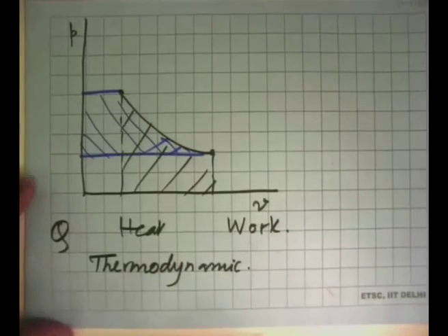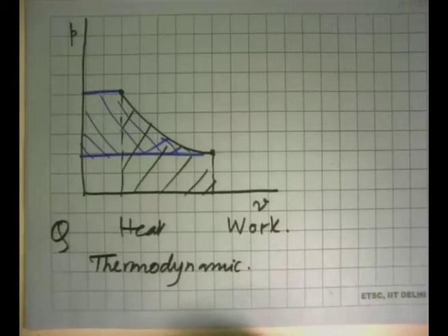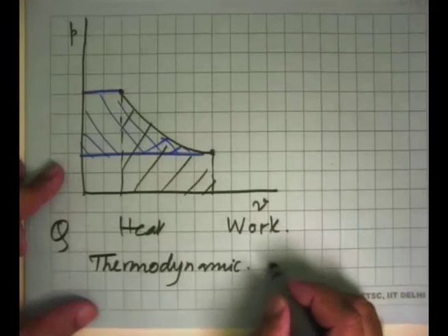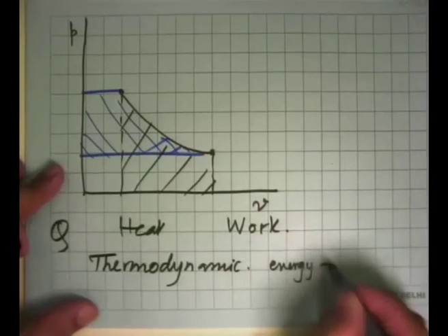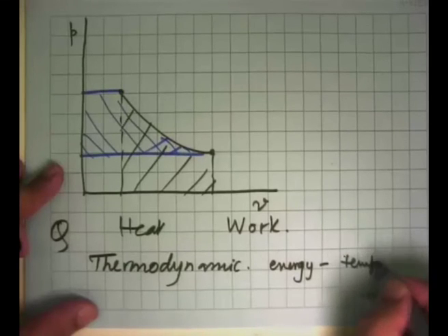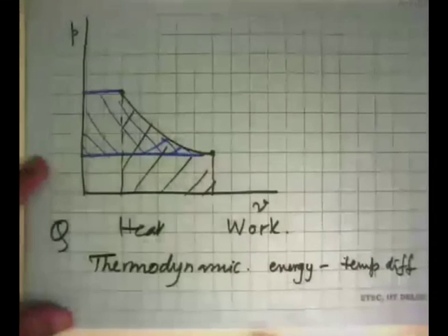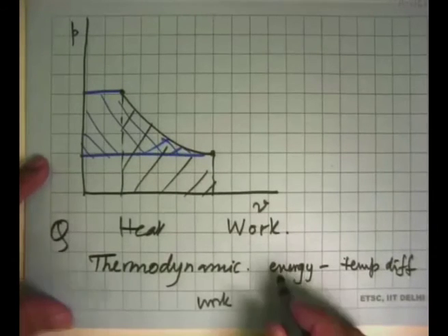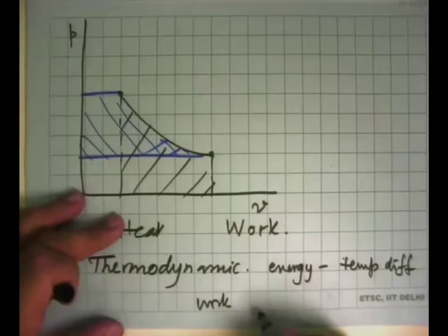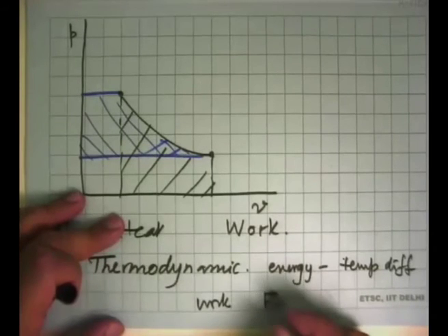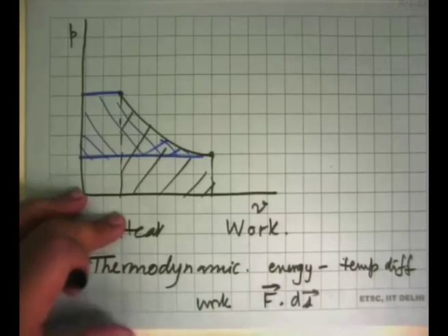of heat and work. And we said that to even define heat and work, we first need to make the system boundary and then ask what is the energy transfer across the system boundary. So heat was defined as that form of energy that crosses the system boundary because of a temperature difference. So it is a transient process and you can see heat only at the system boundary, nowhere else. And we define work as you pushing the system boundary out or in, whichever way, that there is a force into the displacement that the force causes.